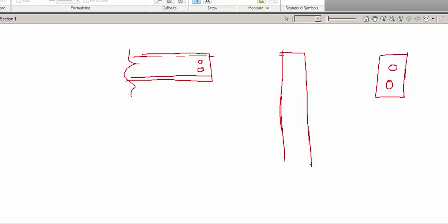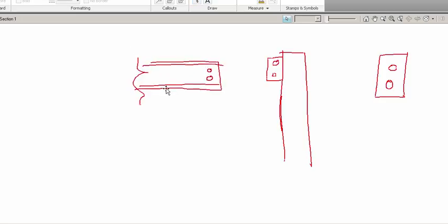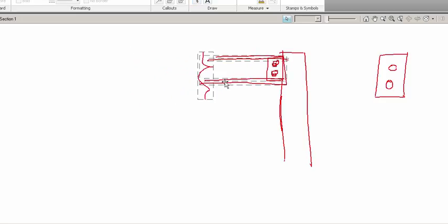You could weld said plate to the column in the shop. And when you get out to the field, you can turn around and bolt this steel beam to that steel plate. And then if you want to, you could add more welding if you needed to. Typically, this is what we refer to as a shear clip connection, or just a shear connection, where there's no actual bending force transmitted from the beam to the column. It's just what we call a pin joint.